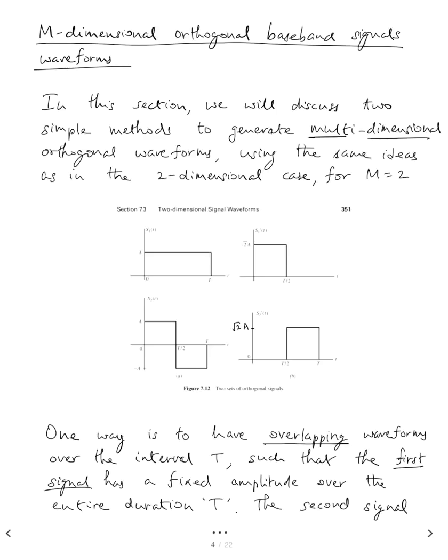Why do we choose the value to be A root 2, or what is the general rule to decide the amplitude? It is chosen so that the energies of the signals are the same. We will elaborate that in the next few pages. So basically we have two ways of creating the orthogonal waveforms.